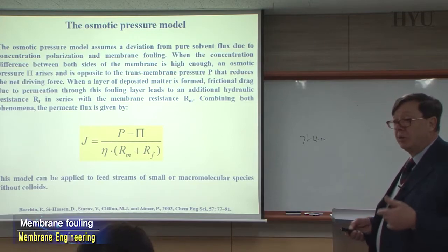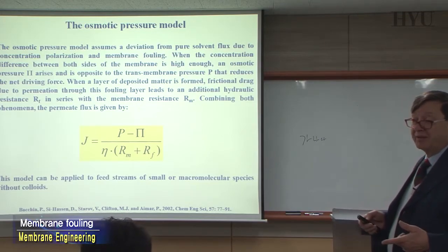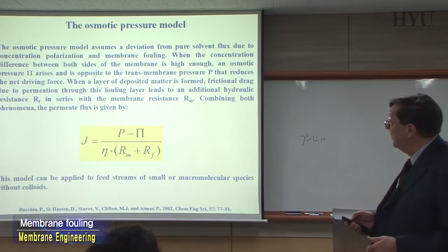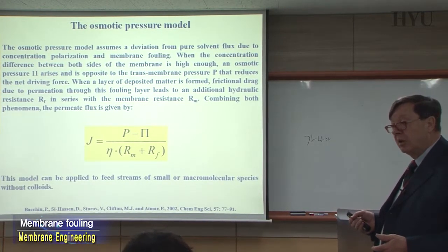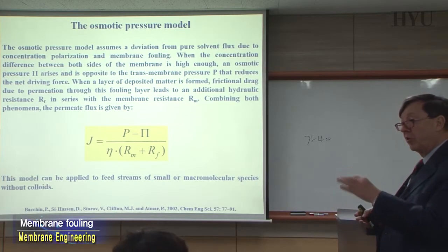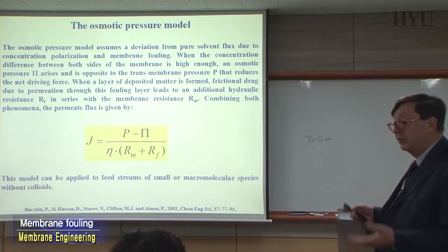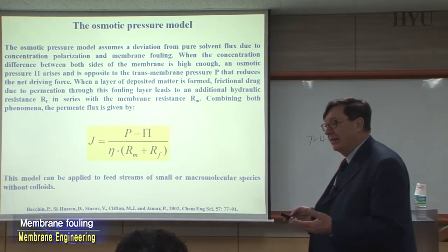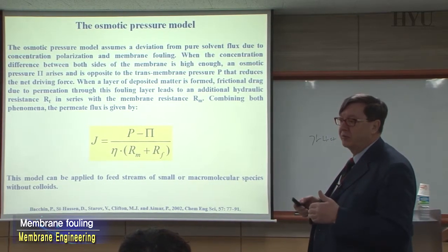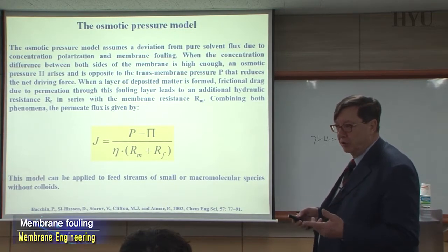When you start to work with microfiltration, ultrafiltration in general, you are assuming that the osmotic phenomena are negligible. And you have big membranes with a big pore, 0.2 microns or 0.01, etc. You are assuming there is no phenomena related to the buildup of polarization, concentration polarization, and so on.